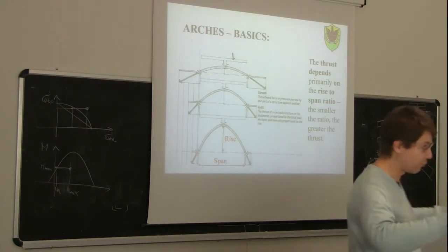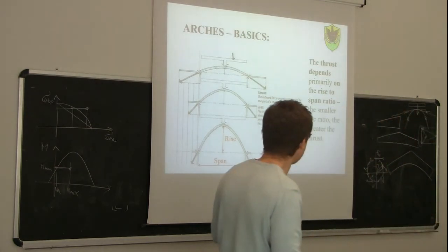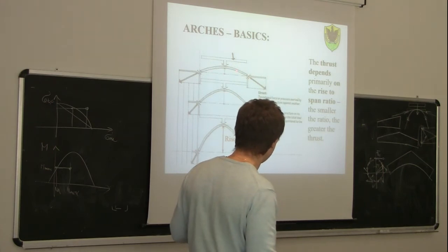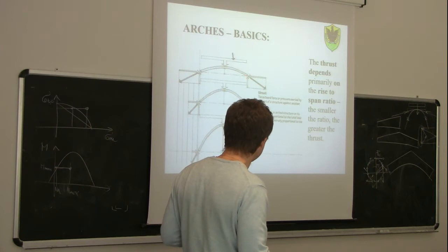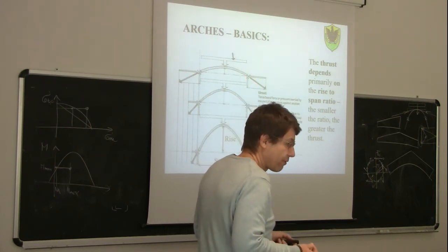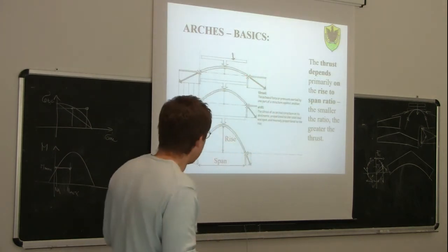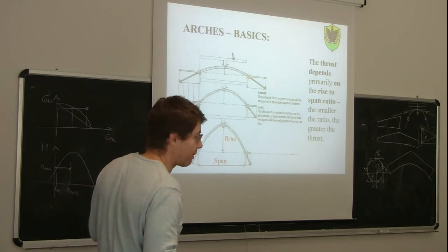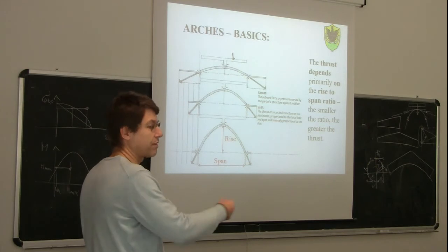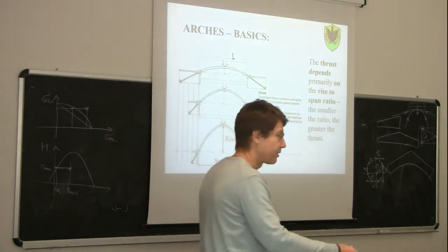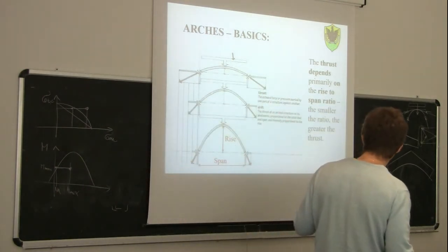Because of course, the problem, again, when you have very high thrust, is that if this foundation is not very well designed, immediately you get a displacement. As you get a displacement, immediately you reduce the compression and increase the bending. So it's very important that this restraint reaction is taken by the foundation.